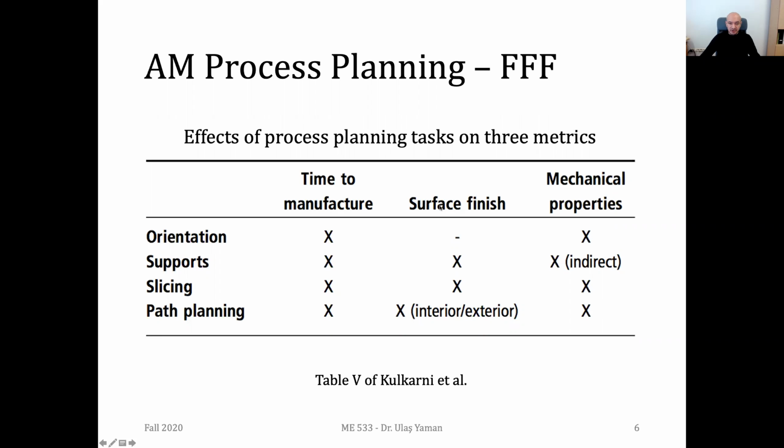And let's have a look at surface finish, the overall quality of the surfaces. Obviously, supports will have a direct effect on the surface quality since they have connections to the surfaces. While removing the support structures, you may harm the surface and increase their roughness values.